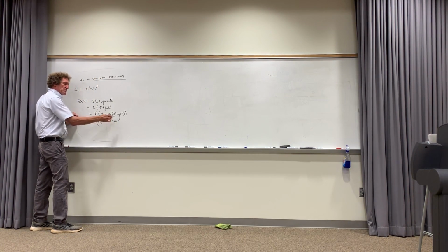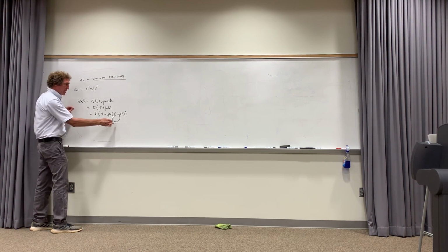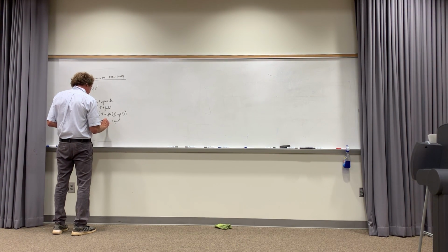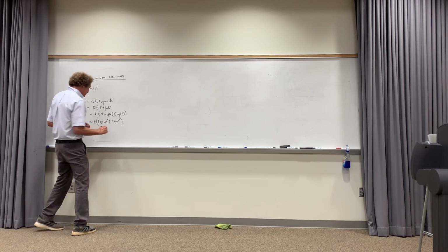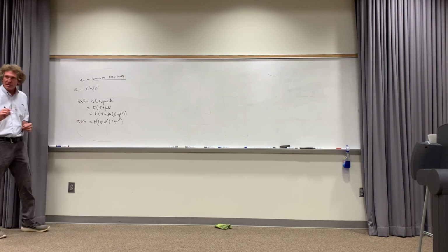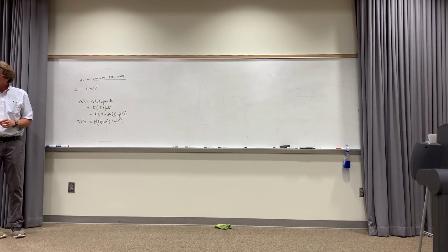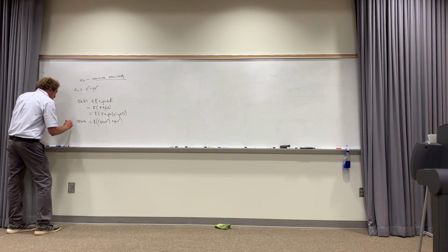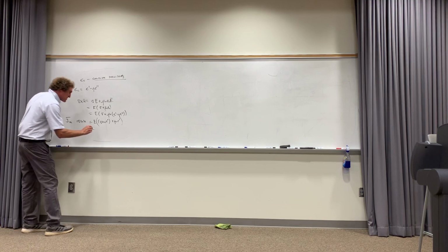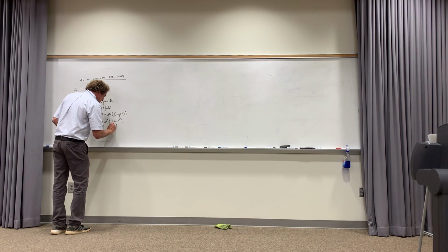But what happens when I have J times J? What is that? It's minus 1, isn't it, class? Well, I've already got a minus sign, so it becomes plus. So I get this, plus omega epsilon double prime here. Now, I broke it out this way for a reason. Remember what I called this curl of H? I gave it a particular name. Anyone? The Maxwell current density, because it has both real and imaginary terms. And note these are associated with loss, and this is simply displacement current.